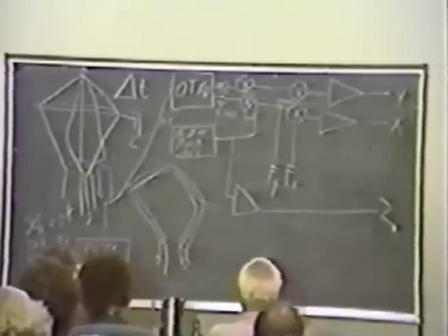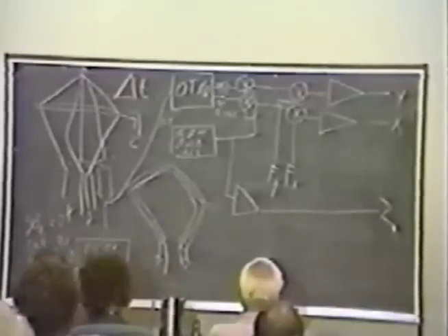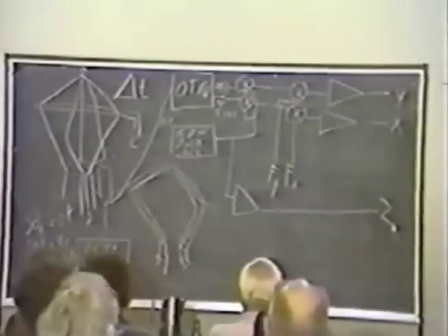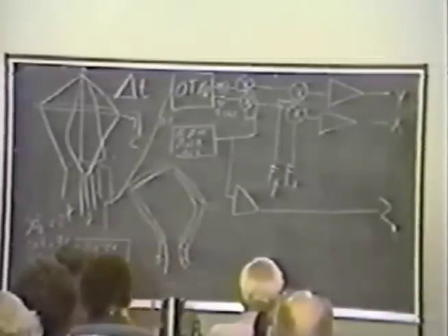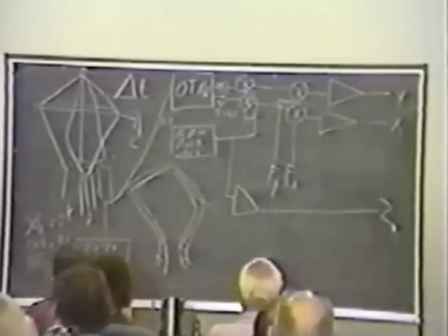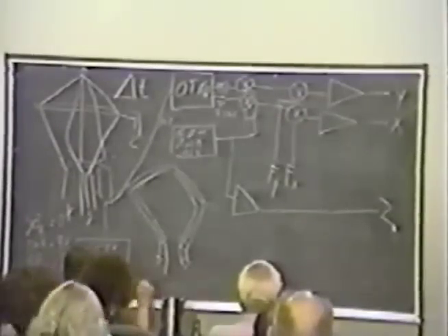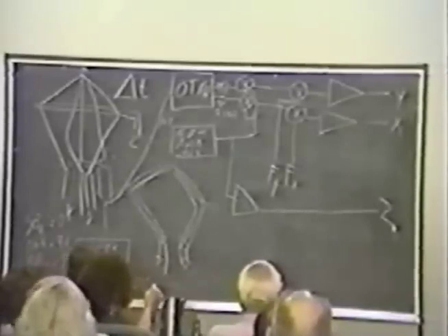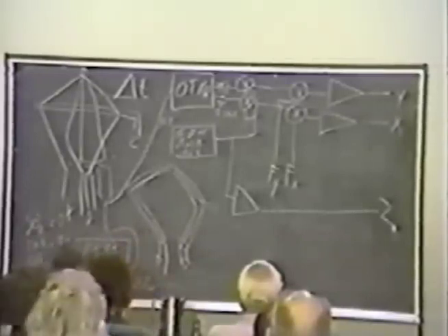We put into the upper sideband F of Y. We put into the lower sideband F of X. Now, at the same time, we take this transmitter and somewhere in the amplifier chain, we put a gate or a mixer, and we put our white noise. We take the output of the transmitter, put it into this RF switch.